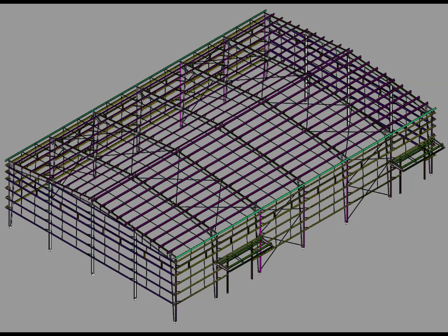The important thing here is not to confuse a sag rod with a roof purlin. The purlin is a primary-secondary framing member that supports the roof sheeting. The sag rod is a much smaller supporting or stabilizing member associated with the purlin arrangement. Therefore, when we are reading a PEB drawing, we should always identify the member based on its position, function, and connection arrangement rather than simply looking at its size.